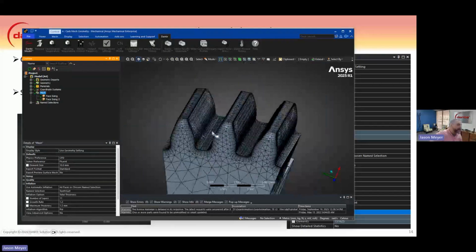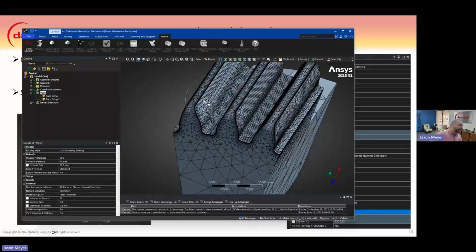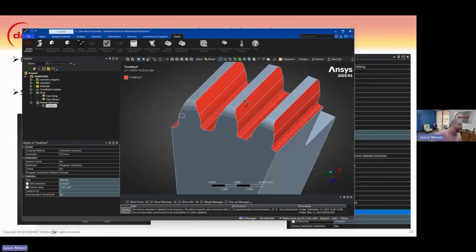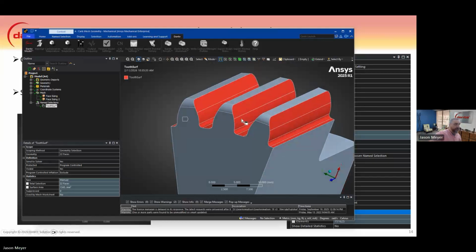This process is going to use a selective carburization process, so it'll go in from the surface, and basically just the flank surfaces and roots will all be carburized here. I have that set up as a name selection here. You can see that will be the carburization surface.